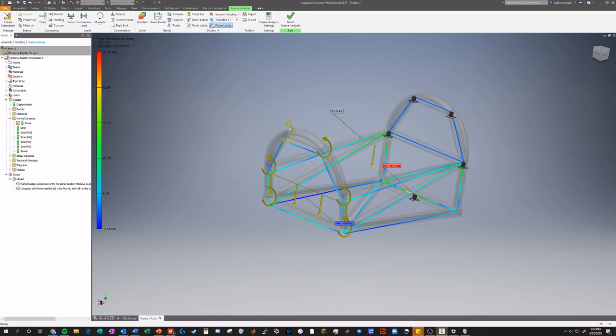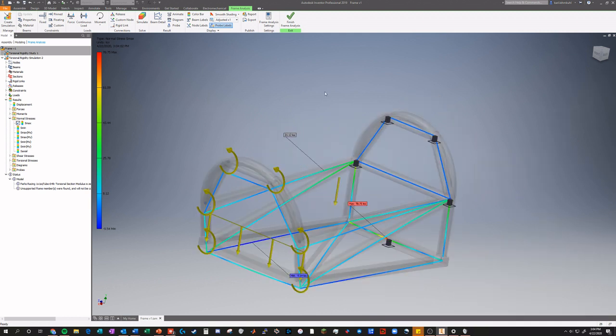It will show me what the stress is at that point. So now, if I wanted to, and what I'd advise you to do is, leave these markers as you change simulation variables and you do your studies, so you have a couple reference points. So pick a couple key areas that are really important, and take some data down for that. We'll talk more about that next time, but this is the screen that you'd take screenshots off of if you wanted to visually represent to somebody what was going on.